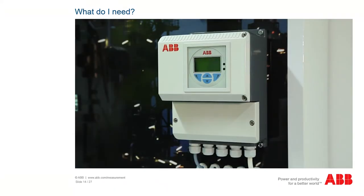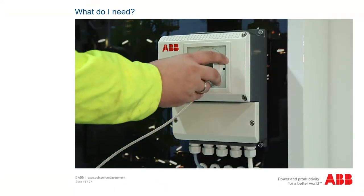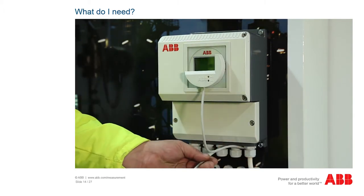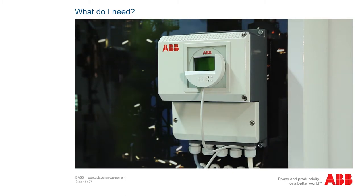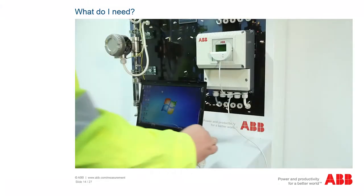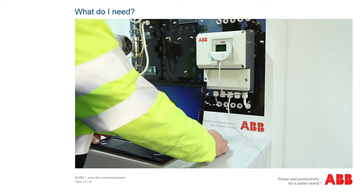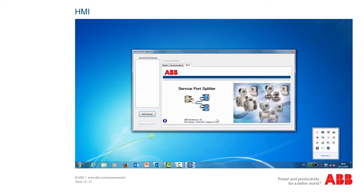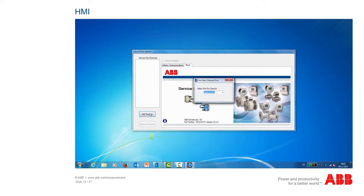The infrared adapter is placed on the electronics flush with the display. To relieve the strain, the cable of the infrared adapter can be placed between the PG glands of the electronics housing. Insert the connector of the infrared adapter in a USB port on the notebook. Now start the service port splitter program supplied with the infrared adapter. The aim is to perform a parameter dump and an alarm dump. However, to be able to read out all of the parameters of the control unit, you must first enter the service password.